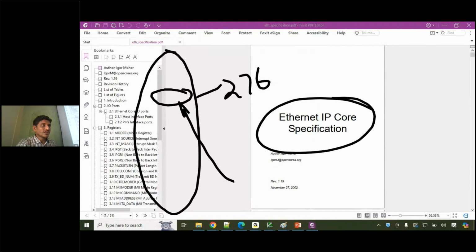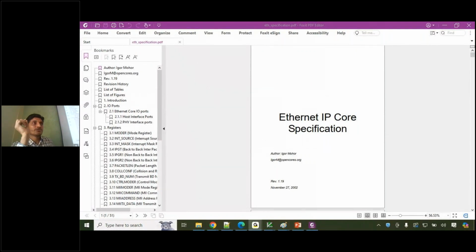So then based on these two inputs, I follow a specific process called functional verification. As part of functional verification, we read through the spec, we list down features, we come up with a test plan, then we develop test bench architecture, we develop test bench components. The logic comes down to this point, where this is the design code.